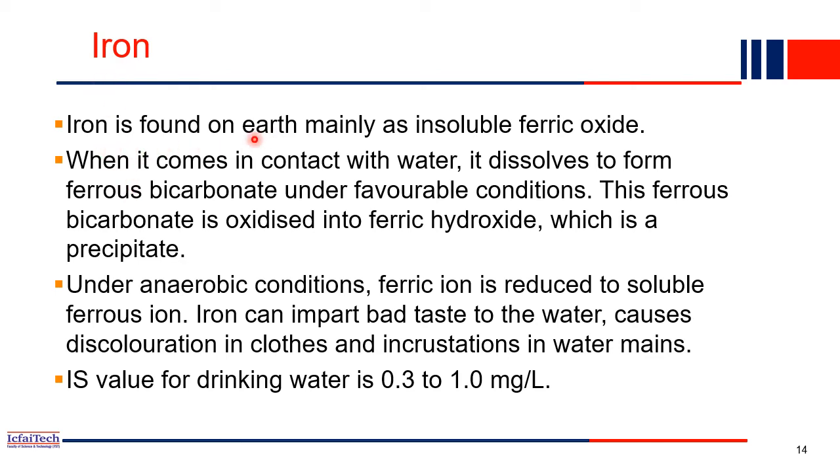So iron is found on earth mainly in the form of insoluble ferric oxide. In nature iron is present, but when it comes in contact with water, it dissolves and forms ferrous bicarbonate under favorable conditions, and this ferrous bicarbonate is oxidized into ferric hydroxide, which is basically the iron present in the water.